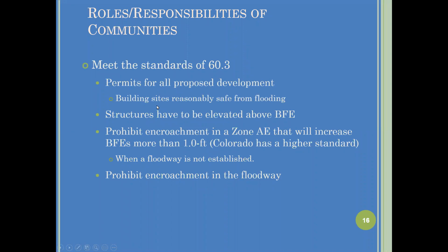Structures have to be elevated above the base flood elevation, and they must prohibit encroachment in the AE zones that would increase the base flood elevations more than 1 foot. Again, Colorado has a higher standard, and prohibits encroachment in the floodway.